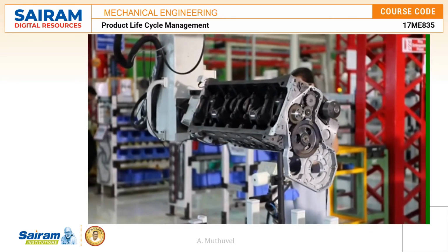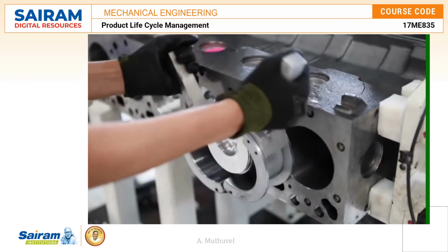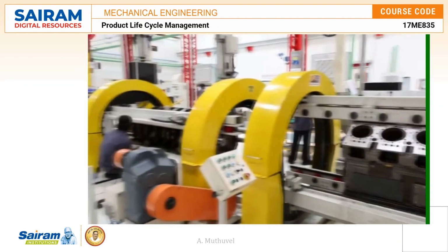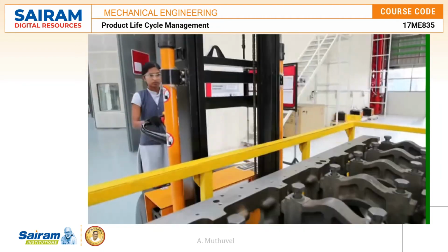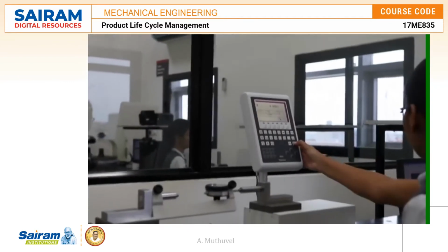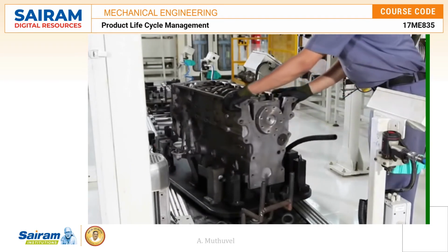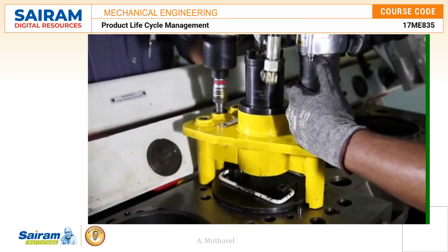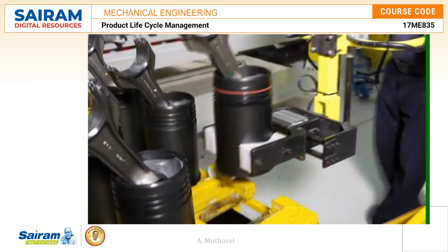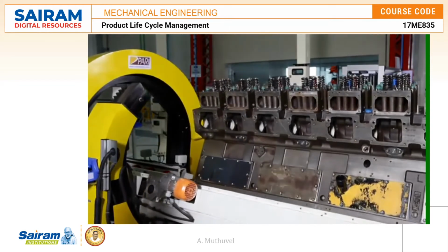After the parts are remanufactured to factory specifications, individual pieces are assembled in a controlled and clean environment. The engine is assembled on a first-of-its-kind rebuilt conveyor line of 9 stations using genuine Cummins new and recon parts. Our assembly line uses fail-safe processes that verify 100% compliance to specification, eliminating defects. Each station has sophisticated equipment such as liner pushers, 2-spindle nut runners, pneumatic wrenches and manipulators. All the major components are lifted using tackles and turnover devices to ensure the safety of parts and people.